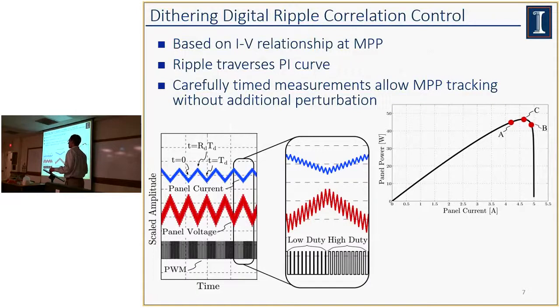I have to think about it a little bit, but theoretically what we want to do is ripple back and forth across the maximum power point. We want the maximum power point to occur over the ripple. Whether we could split that ripple up, maybe, but I don't know if it would be really worth it. Because when you actually start tracking the maximum power point, in the milliamp range, this is rather flat from some perspective. So, yeah.